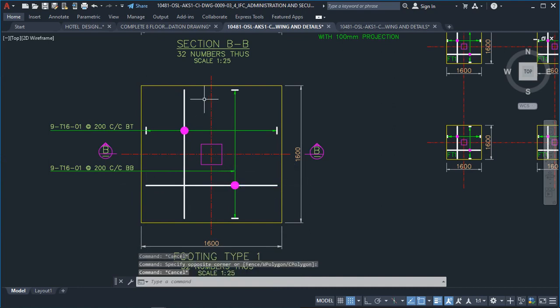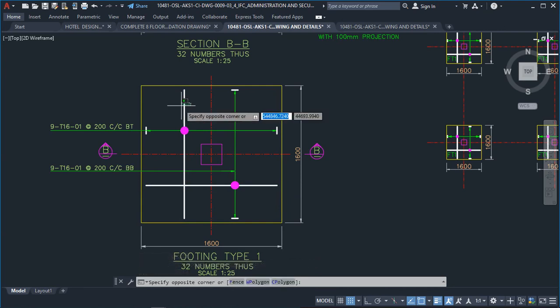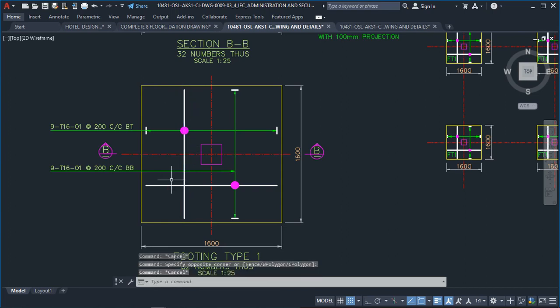A footing base reinforcement must have two types of reinforcement, one coming on the y direction and one going on the x direction. That is why it is usually called a mat reinforcement. So it must have a y direction reinforcement and an x direction reinforcement.